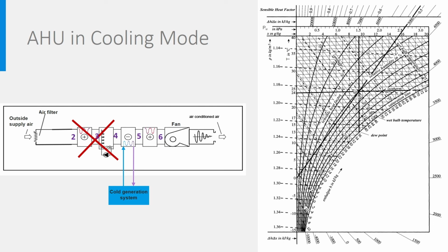Alternatively, it can also be delivered by geothermal cold or cold surface water like sea or lakes. The heat exchanger itself is of the same type as the one we described for heating. In the Mollier diagram, the process of cooling looks like this and results in colder air, but also in much more humid air. The relative humidity has increased up to 85%, which is high.